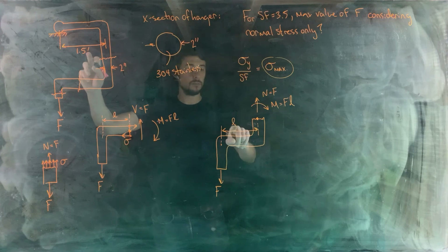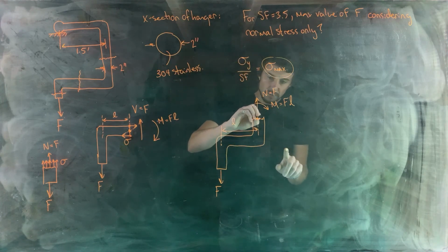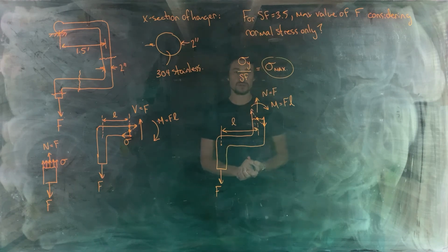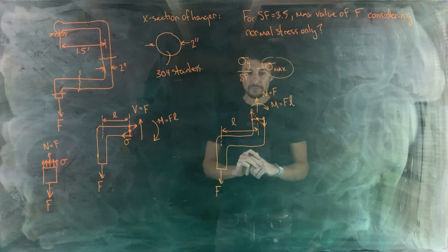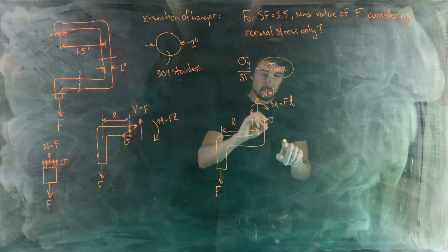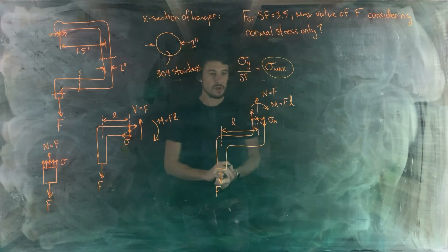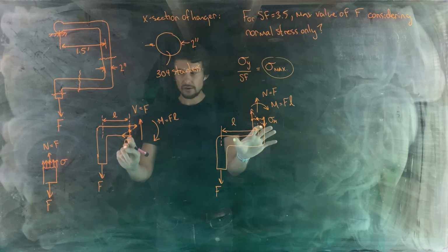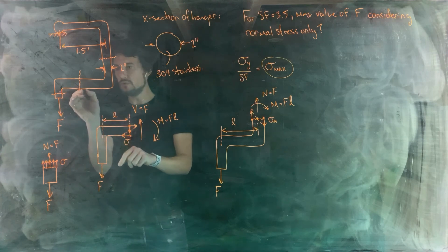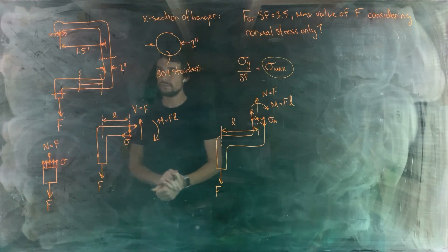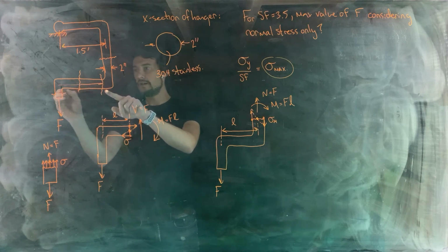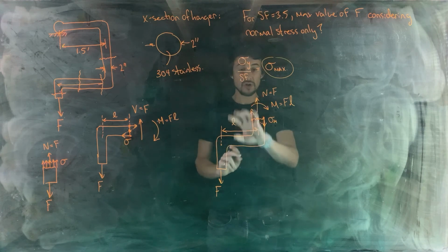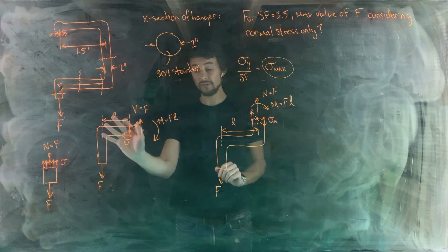And here we know L is 1.5 feet. So again, this internal moment, compression on this side, tension on this side, and a linear transition between those. So thinking about these two normal stresses from our bending moment M, I'll label them sigma subscript M, those are going to be larger than the normal stresses present here because L for this diagram is larger than L would be for this diagram when you keep moving that section cut over right to the corner, right? If you bring it right to the corner, that distance L is not quite equal to 1.5, whereas this L is equal to 1.5. So the moment's larger, so the normal stress is going to be larger. So this is an even better area to look for the normal stress than this is.